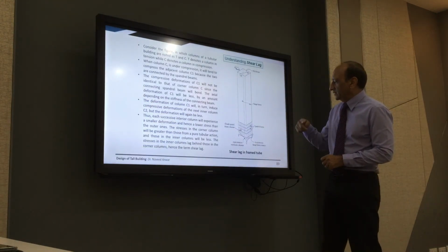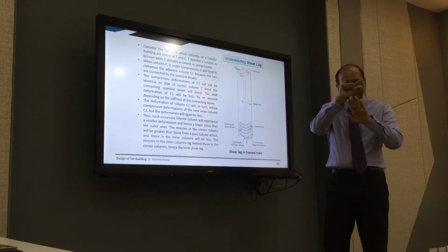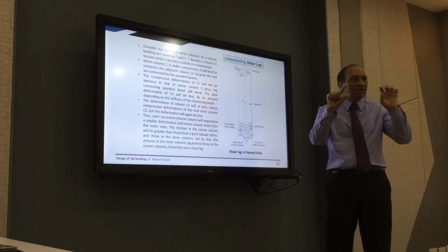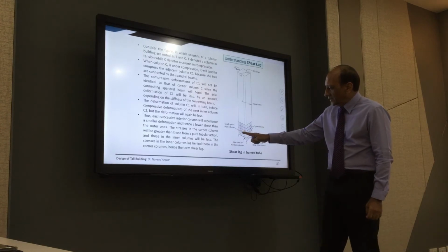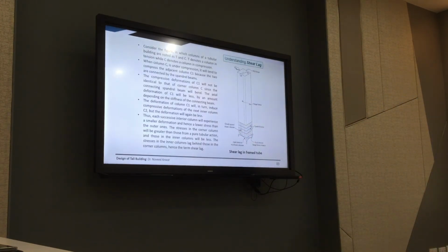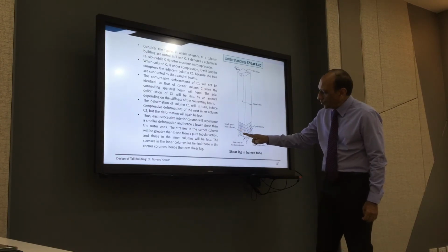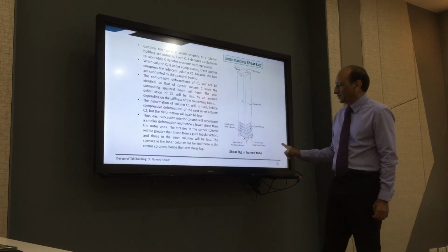This is about shear lag. Same thing: how much shear can the transverse connection carry? That's called shear lag. If the transverse connections are very weak, shear lag will be large. The perfect situation is when you have linear strain distribution, like a beam or a column, and as the shear lag comes, the linear strain distribution becomes non-linear, like that.